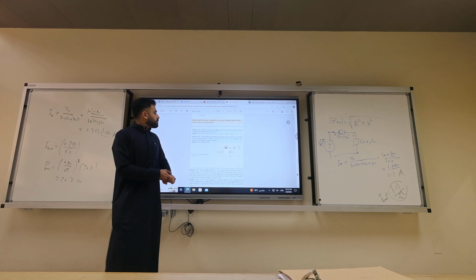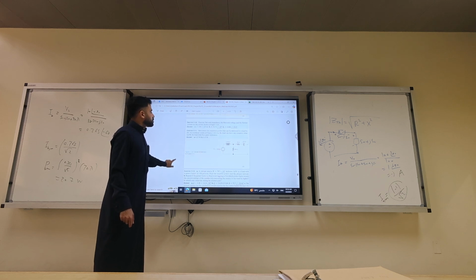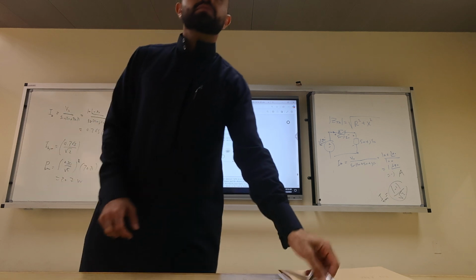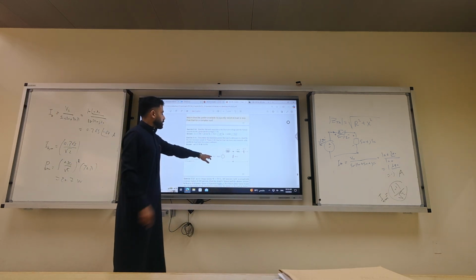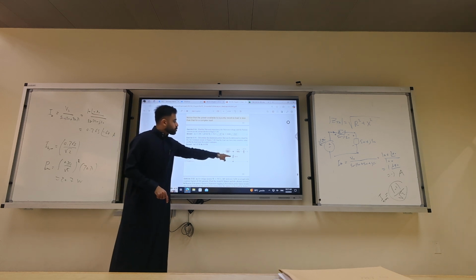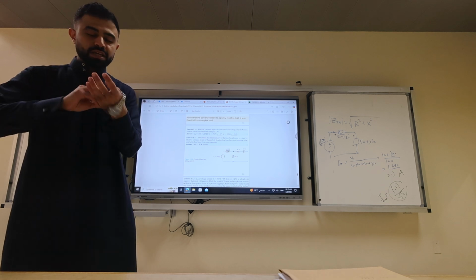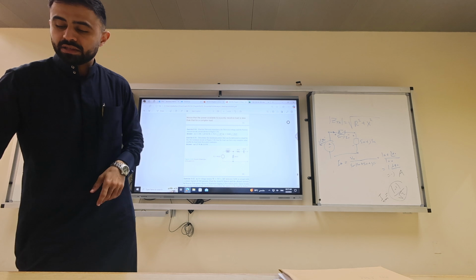Is this the same problem? No, that's a different problem. Okay, let's do it. What's the first step? I always told you about the Thévenin equivalent circuit. By looking, we kill the source. So we kill the voltage source, so it will be 100 parallel with J100. What's 100 parallel with J100? I'm not going to write it now. We can do it fast with a calculator.